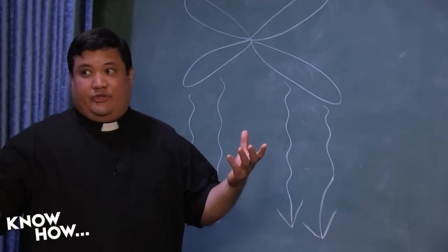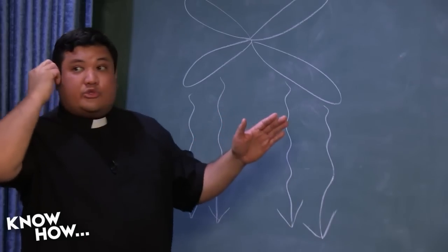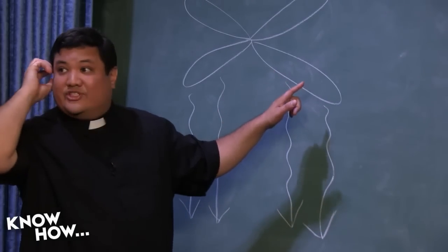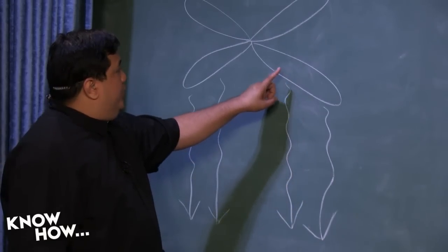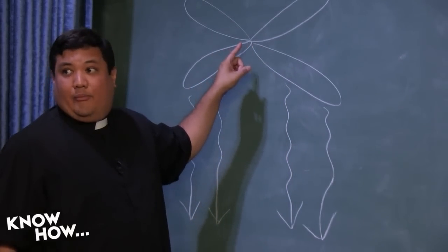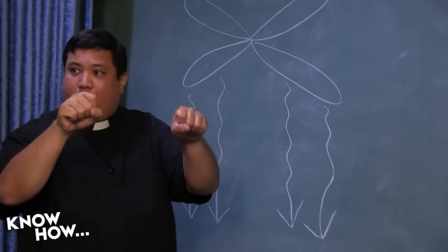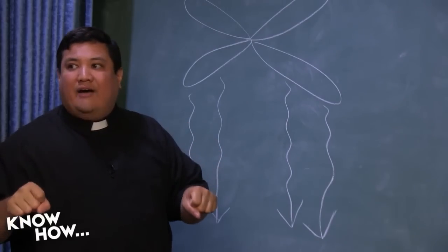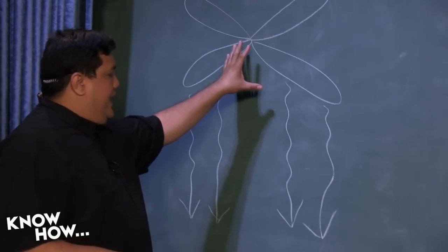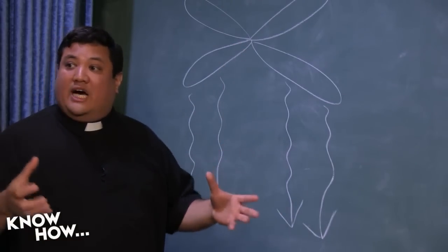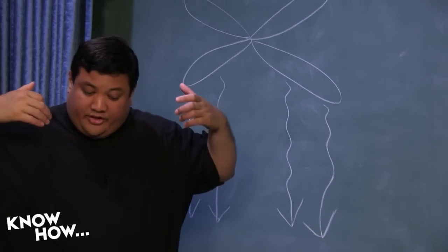This is a representation of what a rotary wing looks like. So imagine that this is spinning around, right? As these surfaces cut through the air, they're forcing air down, developing thrust, lift. That works really well as long as you've got this nice airfoil shape. But as you get closer to the hub and the parts that actually grip the blades, you no longer have that airfoil shape. So there's this empty space in the middle where it's not developing any thrust. There's nothing being pushed down.